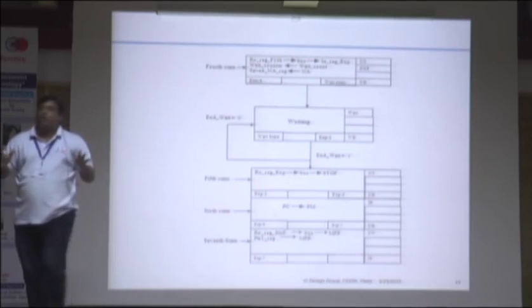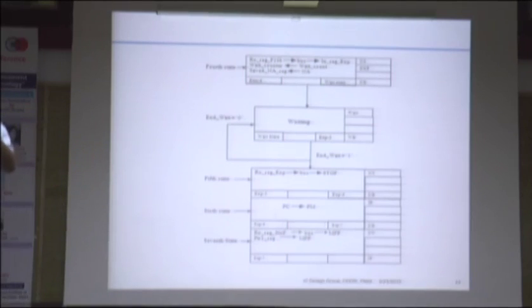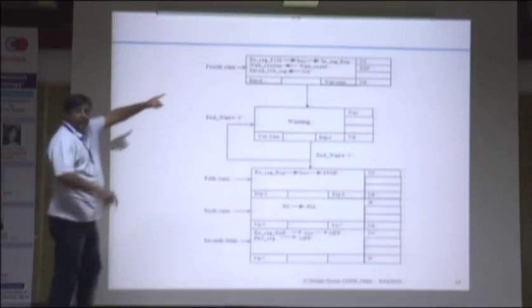Now this exponential block will take 54 clock cycles to compute the result. It takes 54 cycles to compute, okay. So the next state, now the processor has to wait for 54 clock cycles. When you have loaded, this processor goes into the wait state. Now it is waiting for the result to come. So this wait count is 54.